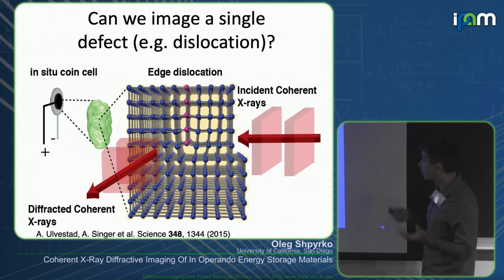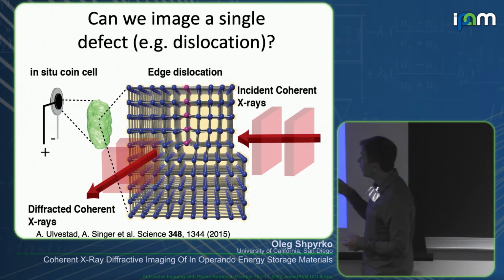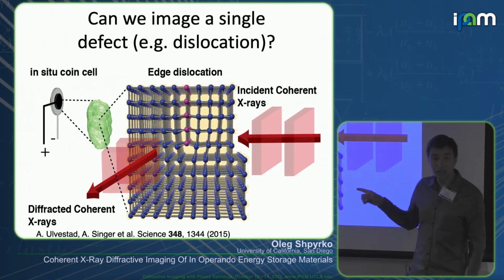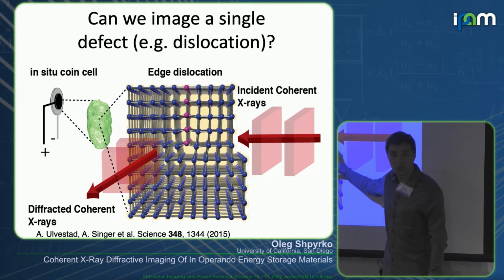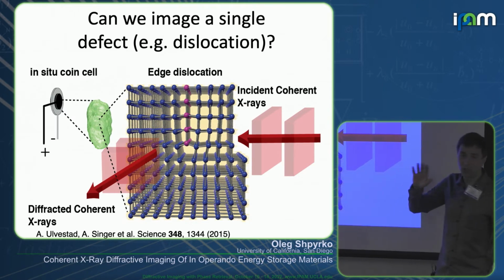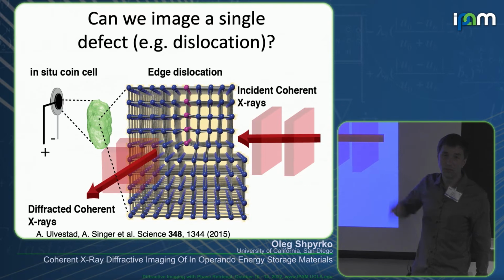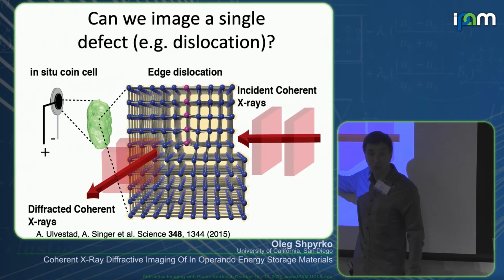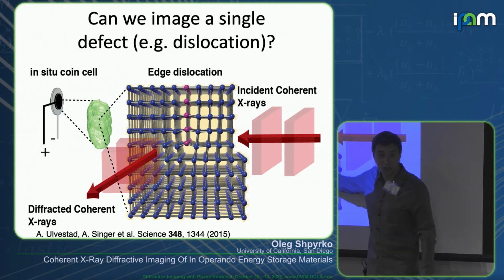The reason why they're important is that in a lot of the oxides, these edge dislocations can provide a very fast way for the ions to diffuse through. And it's not just for energy storage materials, but basically you can take STO and look at oxygen diffusion. And the oxygen diffusion, once you create enough dislocations, will be very fast this way, will be actually worse off in the other direction, right? It's kind of like a little super highway.